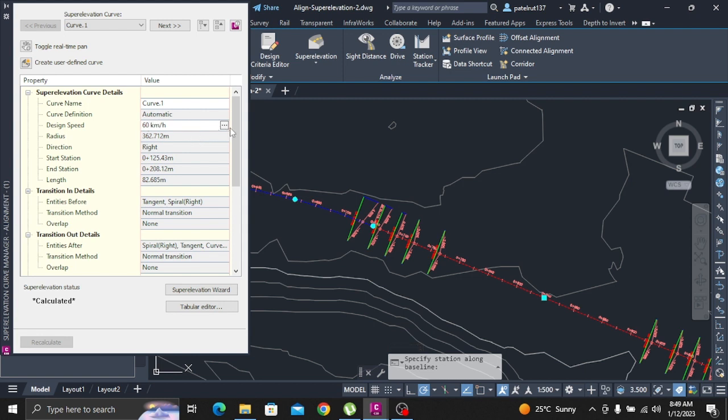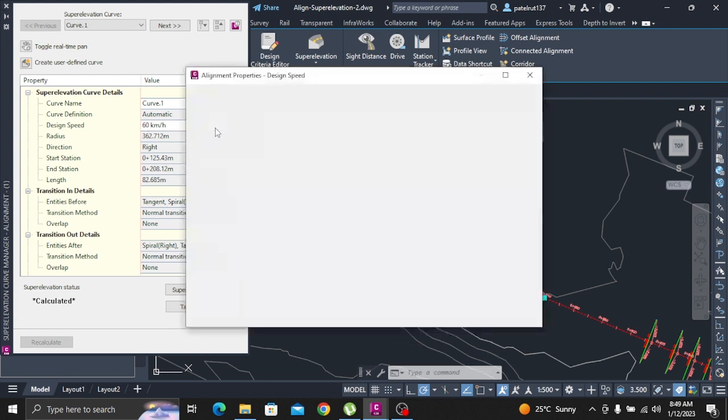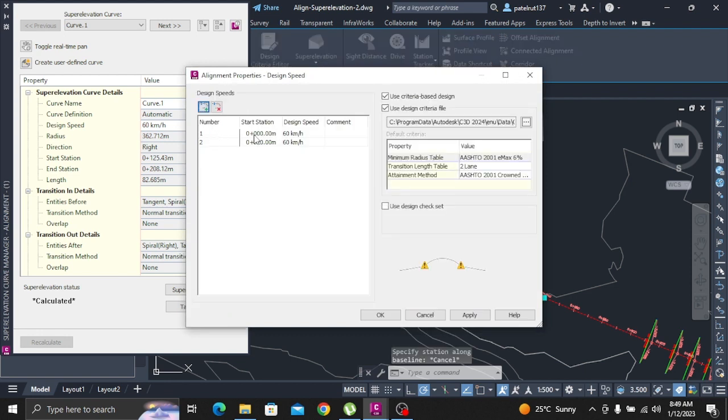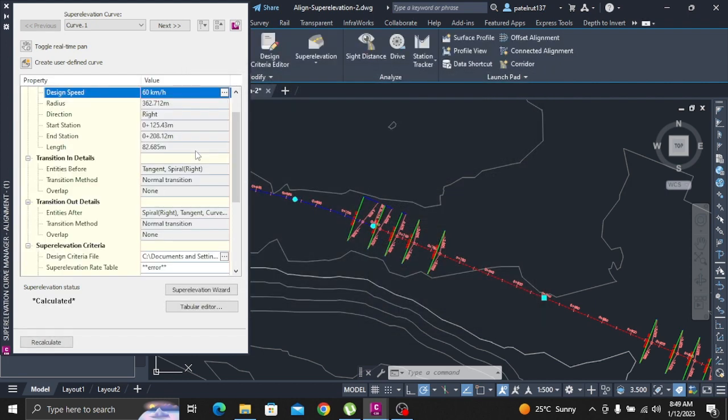Scroll down to the Superelevation Criteria category. Expand the category. Right-click the Normal Shoulder Width row. The Apply to Entire Alignment option enables you to update the design criteria at a curve, and then quickly apply the change to all curves in the alignment. Right-click the superelevation criteria row.